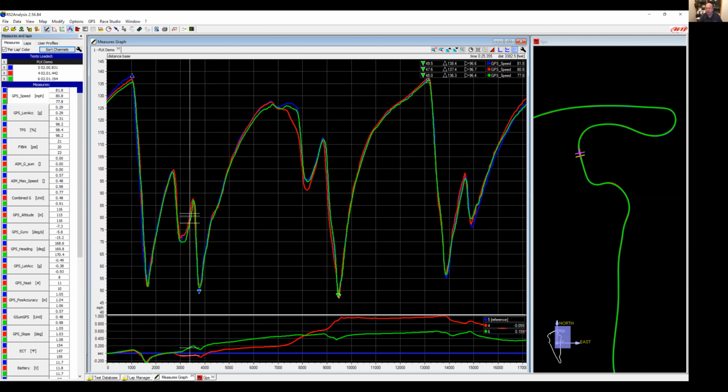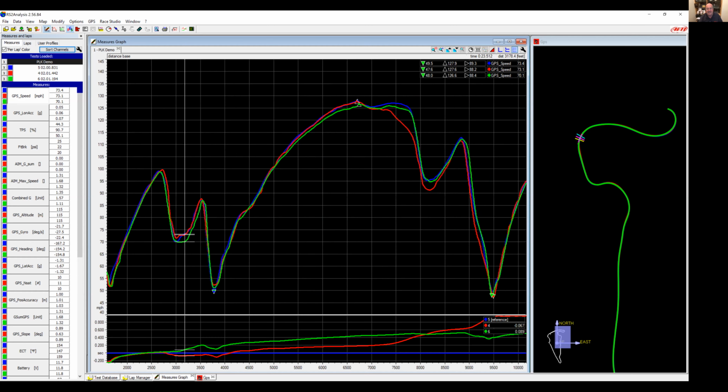All right. Right now, all 3 laps are that far apart right here. Now, obviously turn 3, I'm having trouble. Turn 3, I really need to get a better idea, and I need to be more decisive in the turn in, and I need to hit my marks first and foremost, and I need to go to acceleration. Now, the very fact that the red lap speed comes up a little bit sooner and doesn't go down as far initially, I'm gaining speed going in, I'm maintaining it coming out, okay? Anytime these are parallel, the 2 laps in comparison are the same.